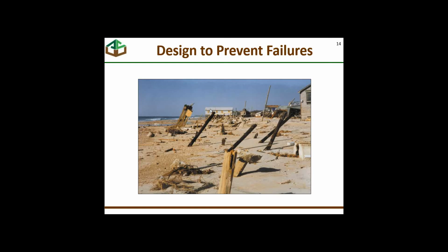Now there are some embedment issues here as well. You can see the piles that are leaning here are leaning because they're not very deep in the soil at this point. So they have been allowed to rotate. The load obviously is coming from the water. You see over here on the left, so the loads are coming from left to right. And they have obviously stripped the building off of the foundation, and when they stripped it, they pushed these piles over.